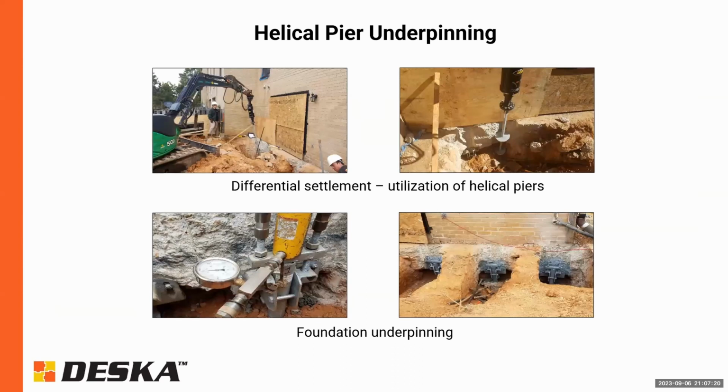And then the lower right picture is essentially several brackets attached to the footing to properly support it, and essentially take the load off of the shallow soil and transfer that load down 20, 30, 40 feet. Just depends on the capacity of the soil.